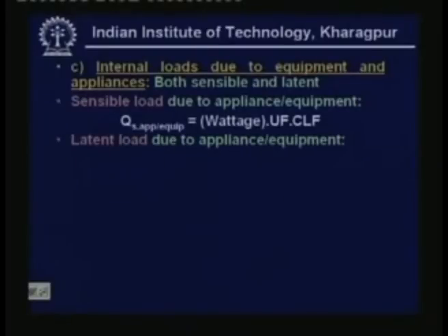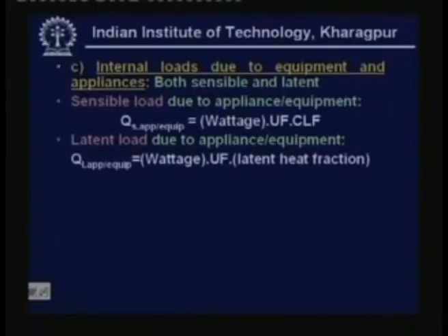And then what is the latent load due to appliance or equipment? Latent load due to appliance or equipment is given by the rated wattage multiplied by the utilization factor multiplied by the latent heat fraction.